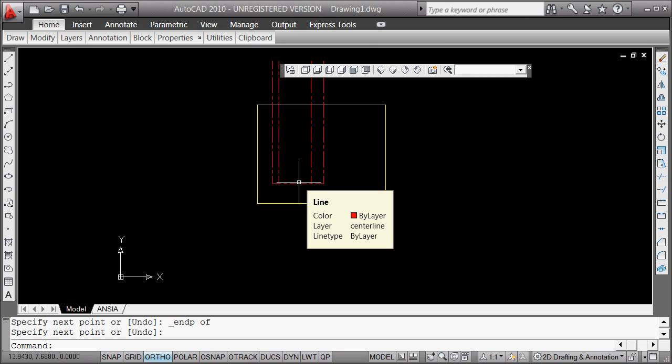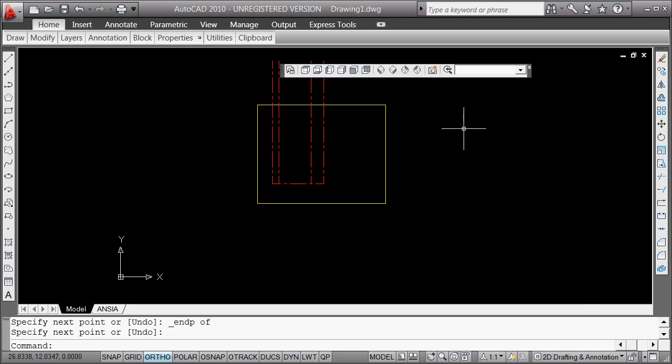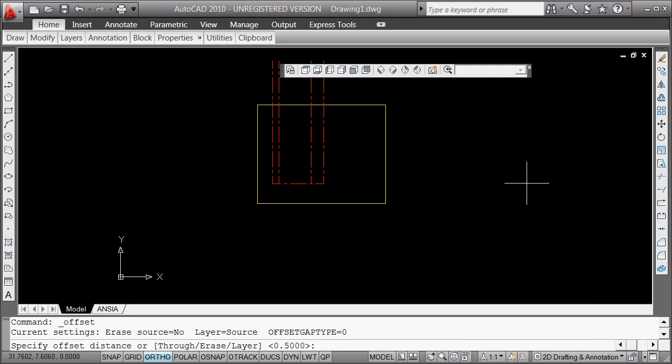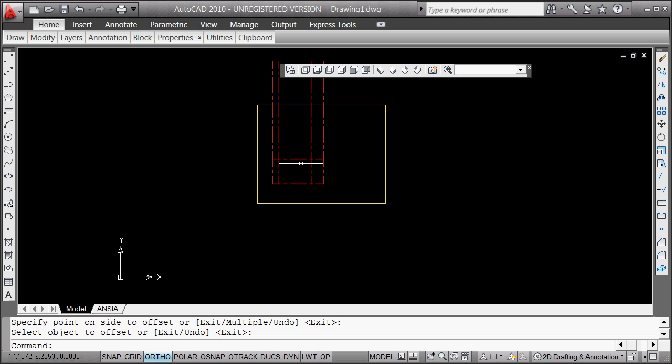In other words, the thickness of the base piece. So I can now say, hold down my right mouse, offset 2. Again, we're just drafting the left side, left piece, so it can kind of throw off your eye a little bit here. That's 2, and then the total piece is 5 tall. So offset by hitting the space bar. Hitting the space bar will remember the last command you did.